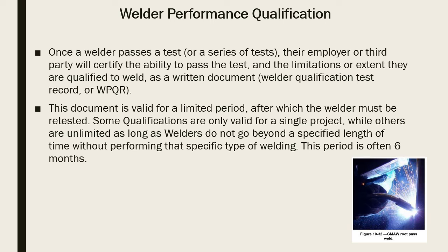But I would just write down that I had seen that. If I saw that guy using that process for the day, I'd write it down on a little piece of paper and say, yep, I saw him. And if a guy hadn't used a specific welding process for a period of time, sometimes we'd set up one weld booth, and I'd make everybody go through there. All right, everybody goes in there and makes a 6-inch long weld so I can see you utilize that process and that you still have proficiency using that process. So, it's documentation. You have the welder tests. Once the guy passes that test, he's good. The other part of this is, it's only good for a limited amount of time. He's got to prove every now and then, within 6 months, that he still has proficiency to deposit sound weld metal using that welding process.